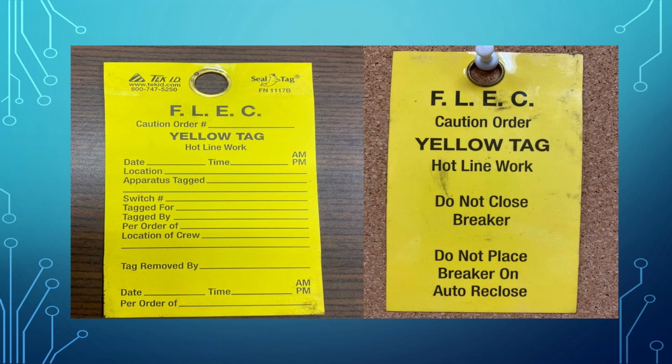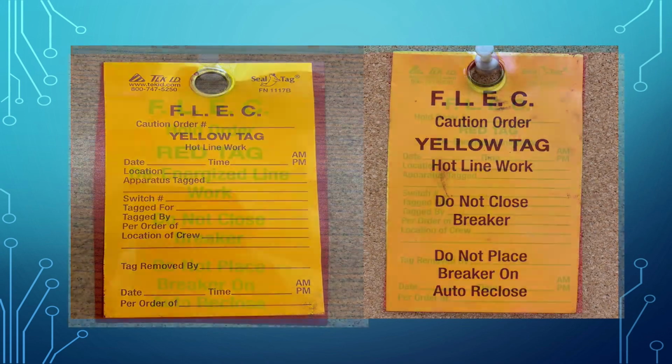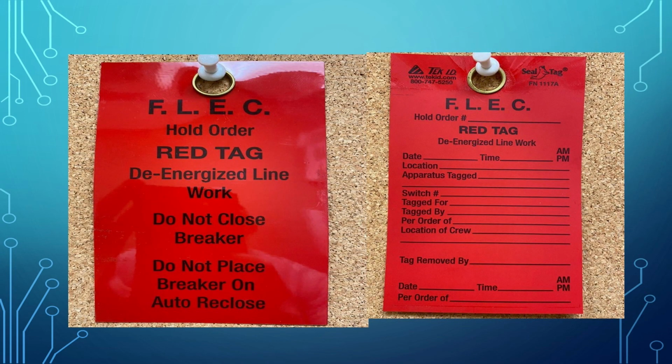Dispatch needs to be in charge of this. And if everybody utilizes the Lockout Tagout procedure, it's, like I said earlier, an excellent buffer between us and maybe somebody getting injured. It's practically the same tag, just a red tag. These mean different things in different locations. Whatever your company policy is, whether you're using the red hold order tags or the yellow caution tags, whichever way you want to use them, it's company policy. Please refer to that and understand it and train our young guys on that.